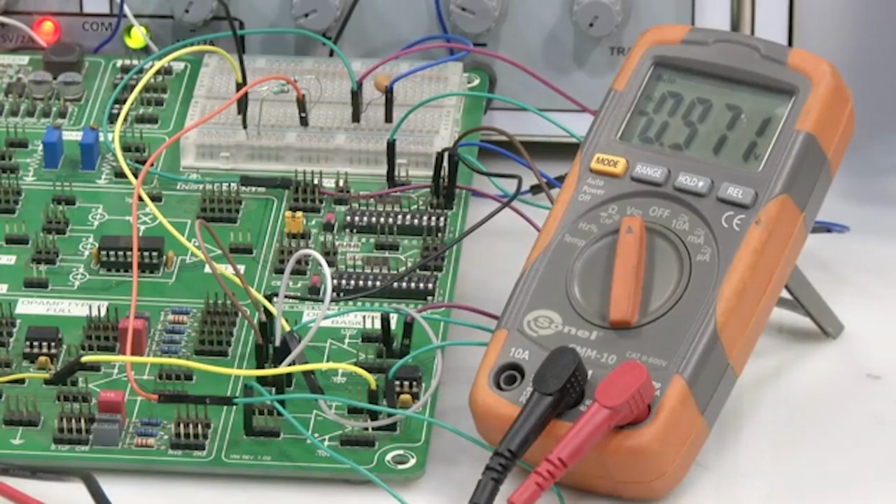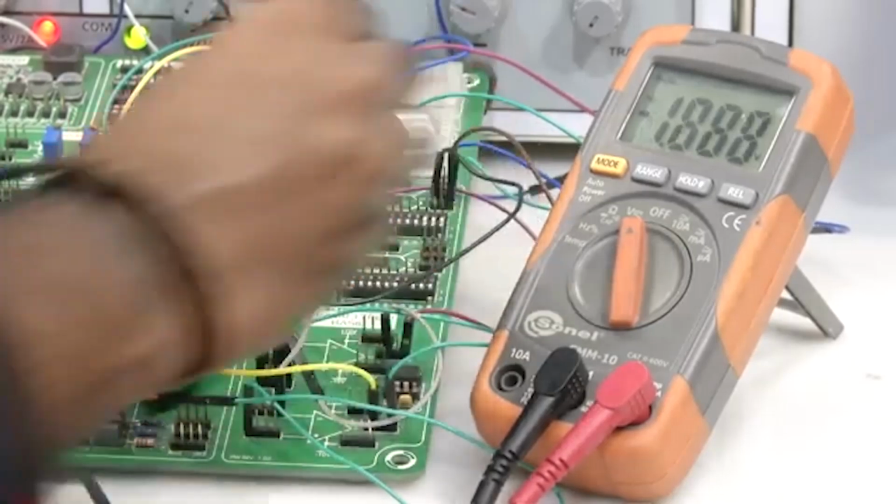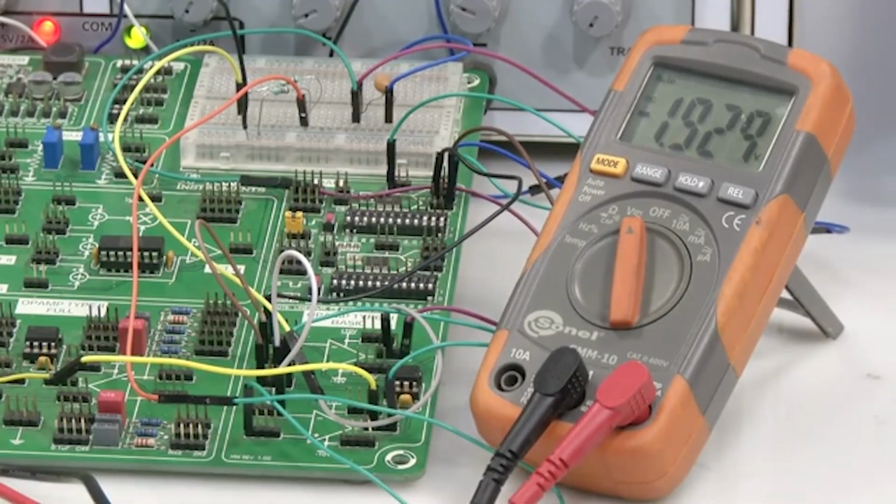See, this way we are able to control the gain. We are seeing a swing from around 300 millivolt to around 0.9 volt, right? That's because our input voltage is very small, because the amplification will be there and you do not want the op amp to go to saturation, correct? I have changed a lot of bits now, so it has gone up to minus 2 volt for 50 millivolt input.